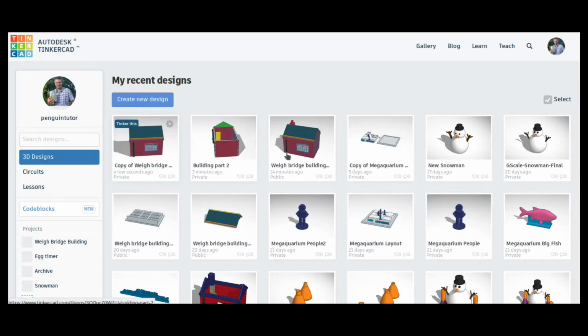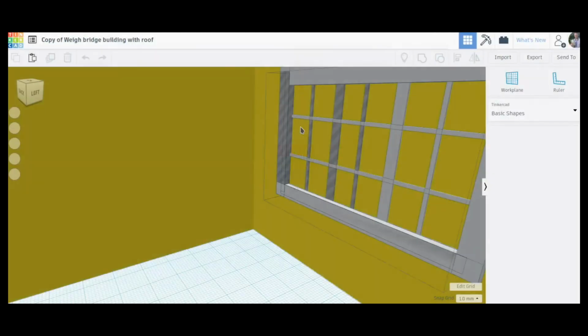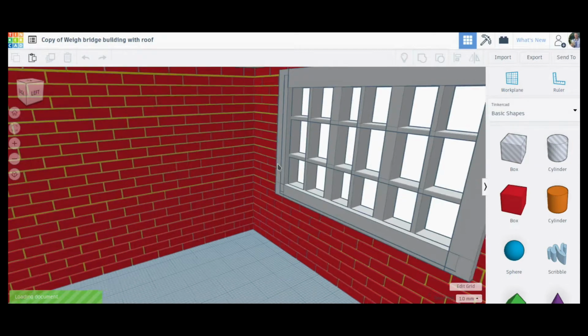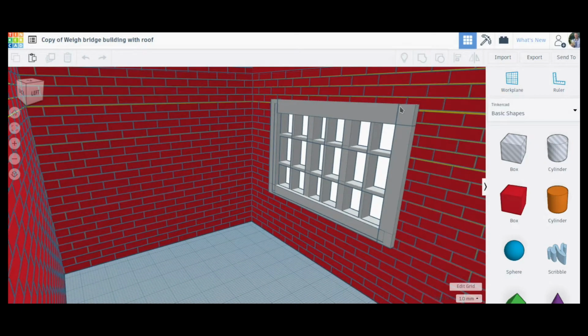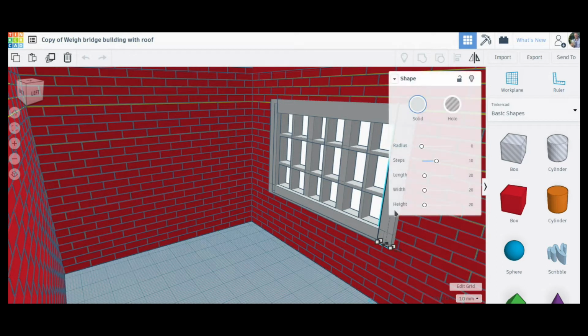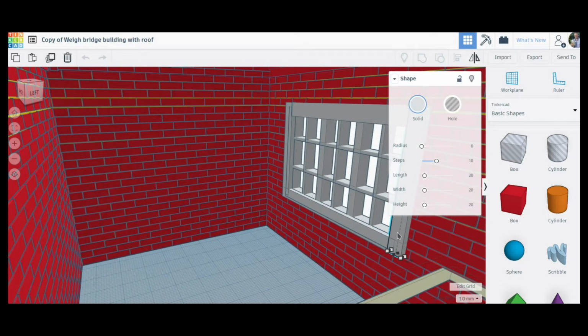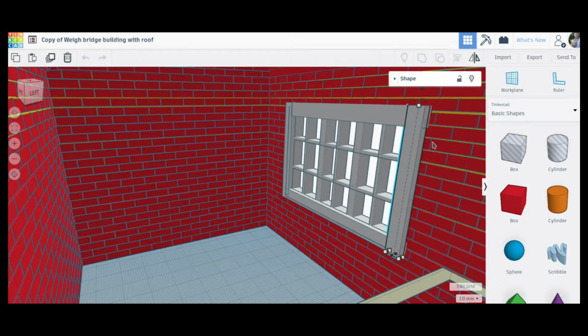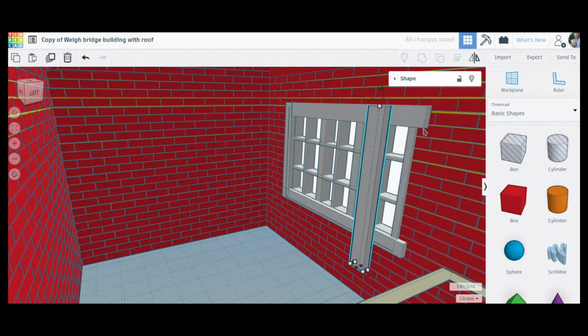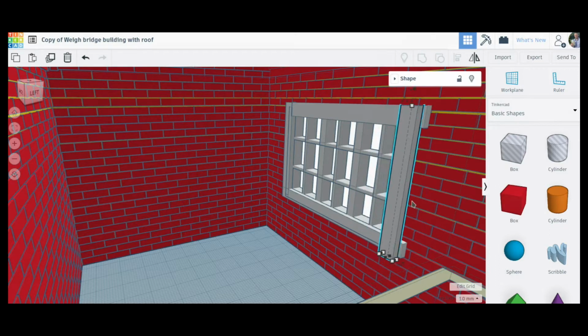Go back to my copy. So when I did the window, I did an overhang on the back. So for instance, if I move this out of the way, you see that this overhangs in the back. That way it gave me a surface that I could glue on when I 3D printed that. And it also gives a slightly wider layer around the back, so that I used a piece of Perspex to provide the see-through glass.